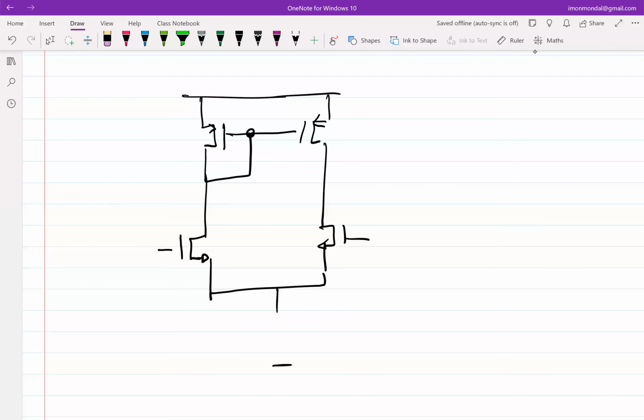Okay, so now let's focus on figuring out what is the output impedance. And for this, I will do the traditional incremental analysis because it's easier to see in that picture, right? So assume that all these constant voltages are shorted, and we use all the methods that we know to find out output resistance.